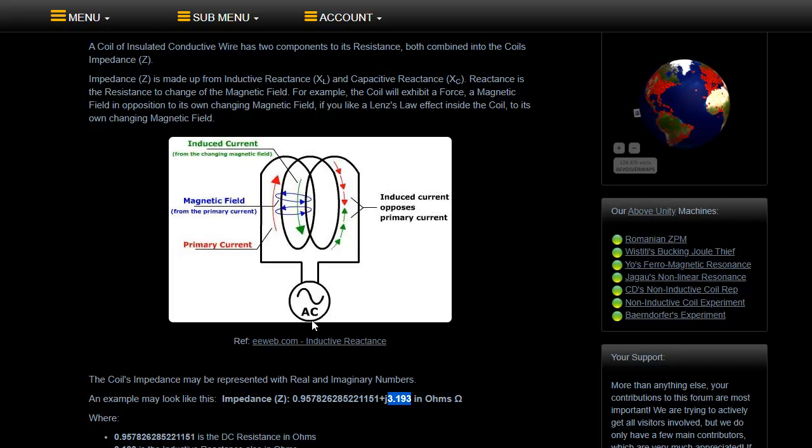So the higher the AC frequency, the more voltage which would be generated between the coils, depending on the applied voltage and the current that's going through the coils and all that sort of thing as well. So it's sort of like Faraday's law of electromagnetic induction on a turn-to-turn level rather than a coil-to-coil or transformer sort of level.